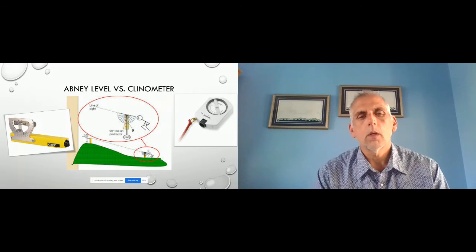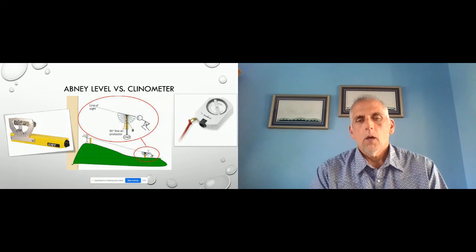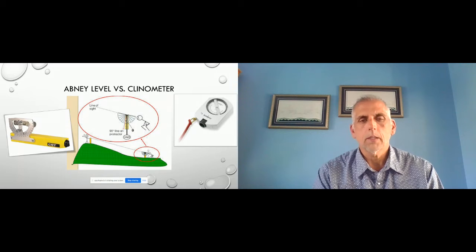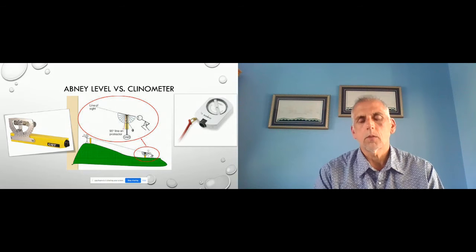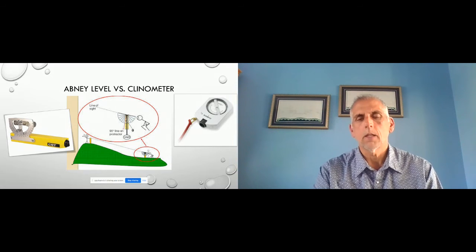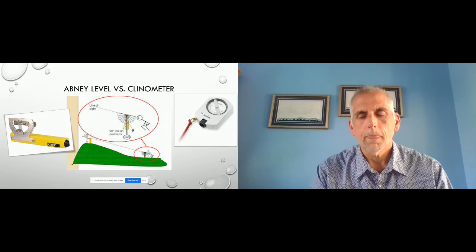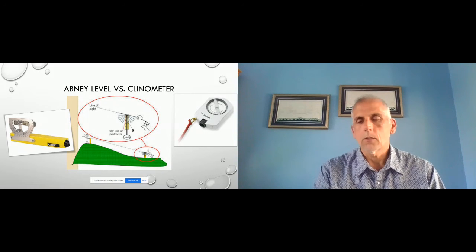Why slope is so important is because we need to know what our slope is to be able to correct for our trench. When we dig a trench on a sloping site, the downhill side may be at 18 inches, the uphill side may be at 22 inches. So when we do our evaluation, we need to know what that uphill depth is going to be to make sure that we're still going to have our separation from trench bottom to an unsuitable horizon. So this is a very important tool that's used out in the field, and we express this out to our centralized intern training. We do a lot with the clinometer, and we do a lot with slope correction because it is so important.